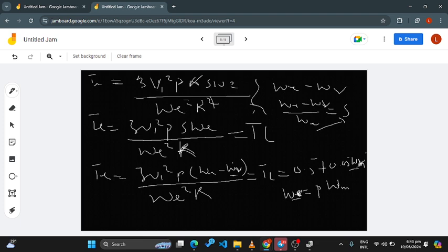Or you come and replace omega m here by omega r on P. Then the answer you get will be the electrical speed, so you still have to convert it to mechanical speed. Is that okay? It's because they all have omega r. That's what is making it confusing.